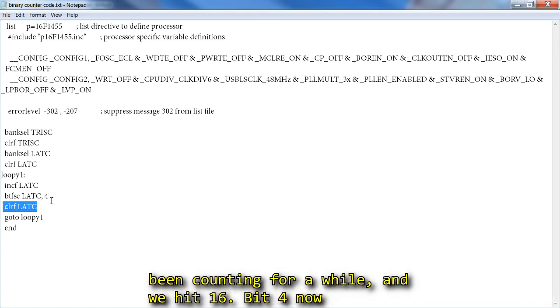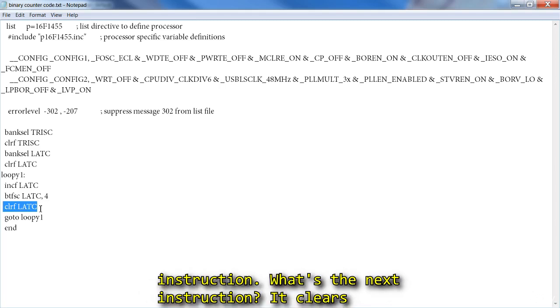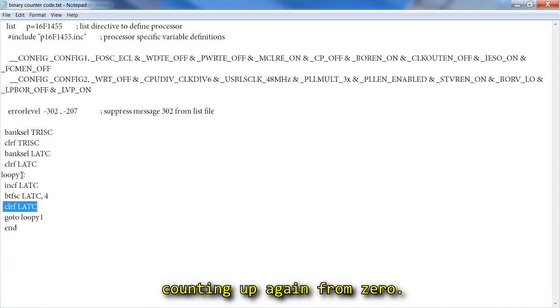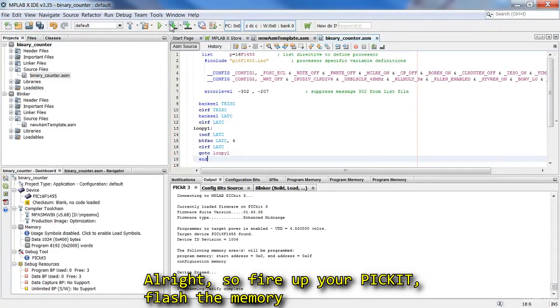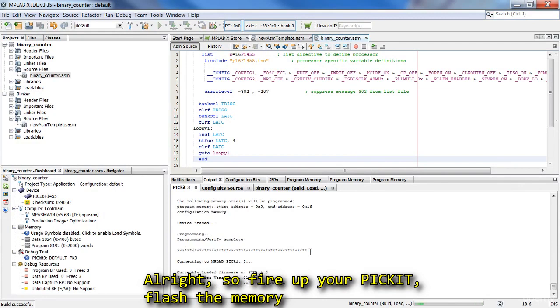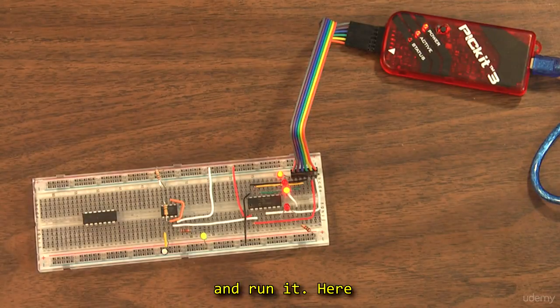So let's say we've been counting for a while and we hit 16. Bit 4 now goes high. We run our bit test, so now it does not skip the next instruction. What's the next instruction? It clears the latch register. It sets everything back to zeros, then loops back to the beginning, and starts counting up again from 0. All right, so fire up your PIC, flash the memory, and run it. So here it is in action.